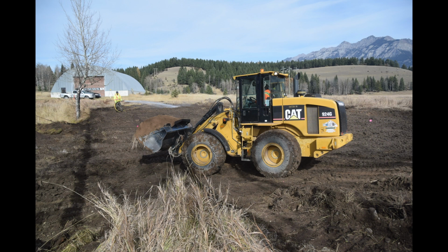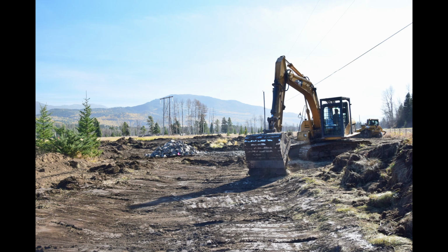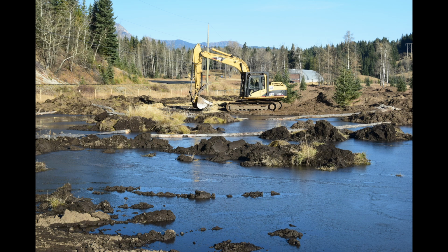We tried everything we could think of to compact the silty soils. This included mixing water with the dry soil and using a large wheel loader with rubber tires to compact the silt in layers. We found it was not possible to compact the silt to form an impermeable layer. I thought the wetlands would hold water even with the silt because there was so much water flowing in the ditch. We built wide spillways over gradual slopes to move water from the ditch into and between the wetlands. Once the spillways and the wetland basins were built, we moved the ditch to begin supplying the wetlands with water.